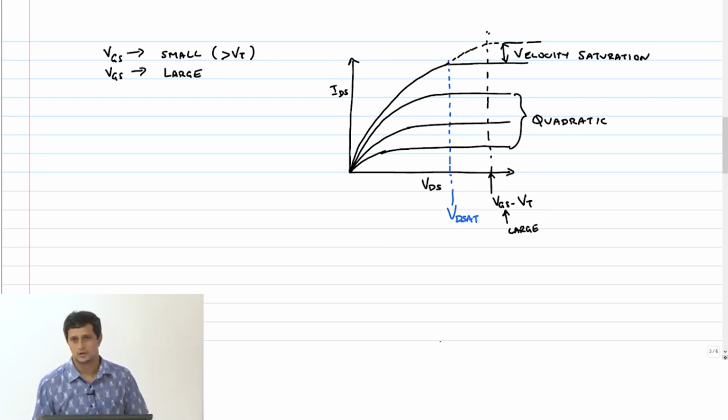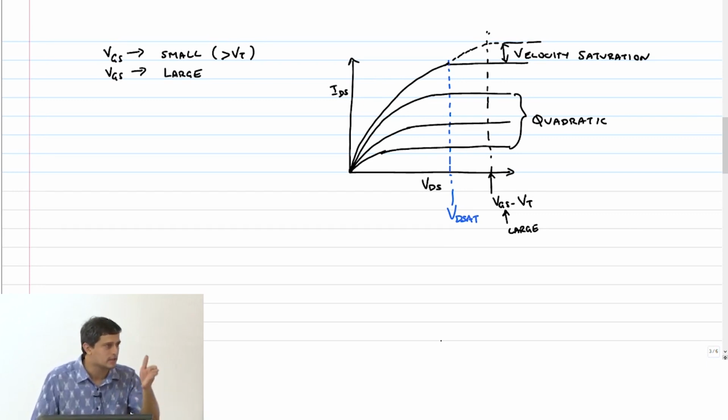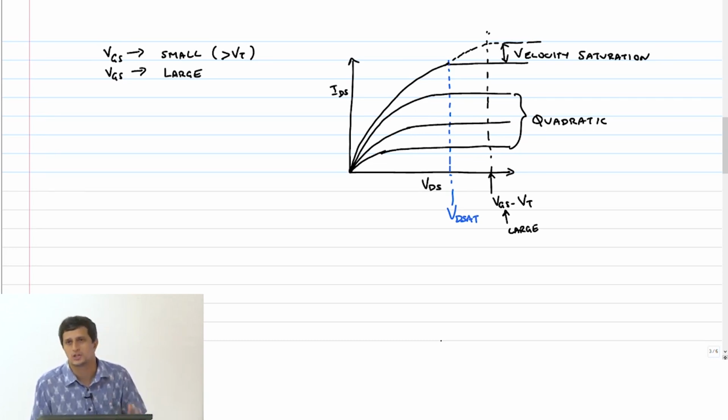Okay. So the point I am trying to make is, it does not mean that a transistor cannot go into the regular saturation region if velocity saturation exists in the technology. It can, it depends on the VGS value, because if it saturates first, then it cannot even enter this velocity saturation region. Basically, if the drift velocity is small enough, then the transistor behaves in the old fashion that we were talking about. So now the question is, for a long channel device, did this velocity saturation effect not exist at all?